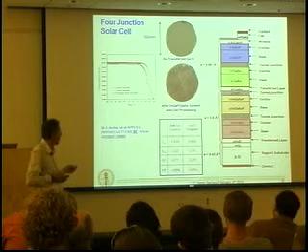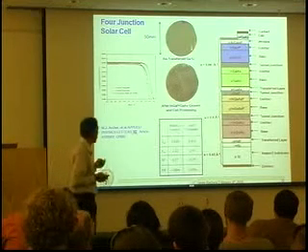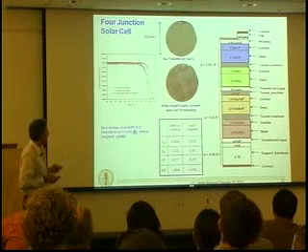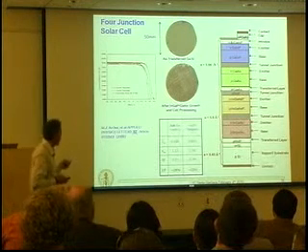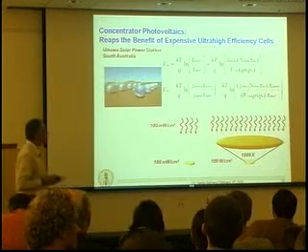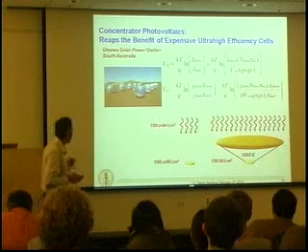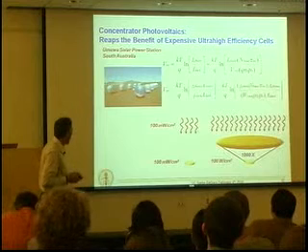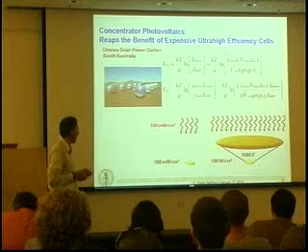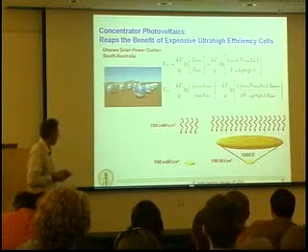And this is actually a fairly significant feature because a lot of the cost of these multi-junction solar cells comes from the expensive substrate. And in this process, we're able to reuse the germanium substrate many times by peeling off these thin layers. Of course, these multi-junction solar cells are expensive at the moment, and they tend to be used in these concentrator receivers where a relatively small and expensive cell can have its cost amortized over a large optical aperture as compared with a flat plate array.